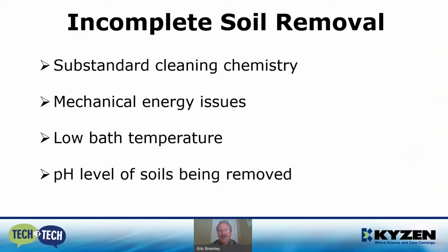Low bath temperature can also do it. If you're not getting the wash bath hot enough to activate the cleaning chemistry or solubilize the heavy oils and greases, again, they'll pass through the rinse and they'll end up as spots or streaks on the parts. Another thing to consider is the pH levels of the actual soils being removed. There are quite a few coolants that are very low in pH and chlorinated, and there are a lot of oils and greases used in the industry today, many of them very aggressive. So the pH level of those can affect the outcome of your process.